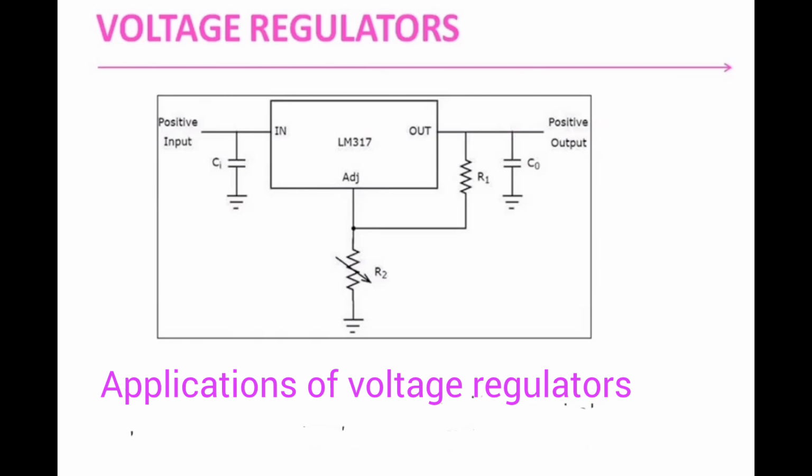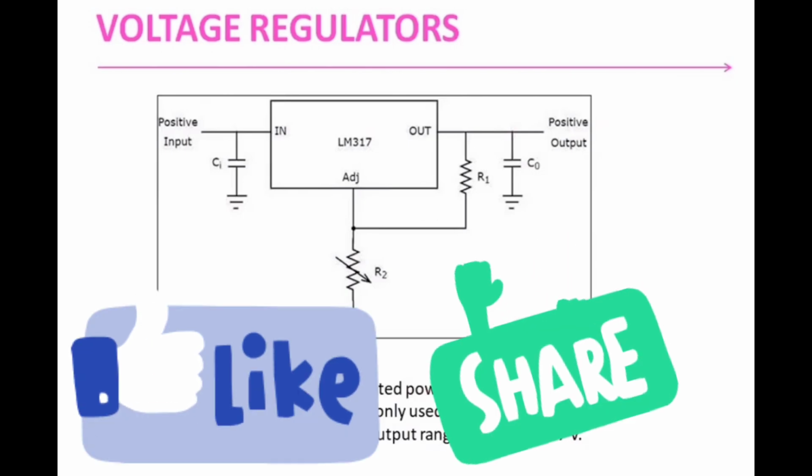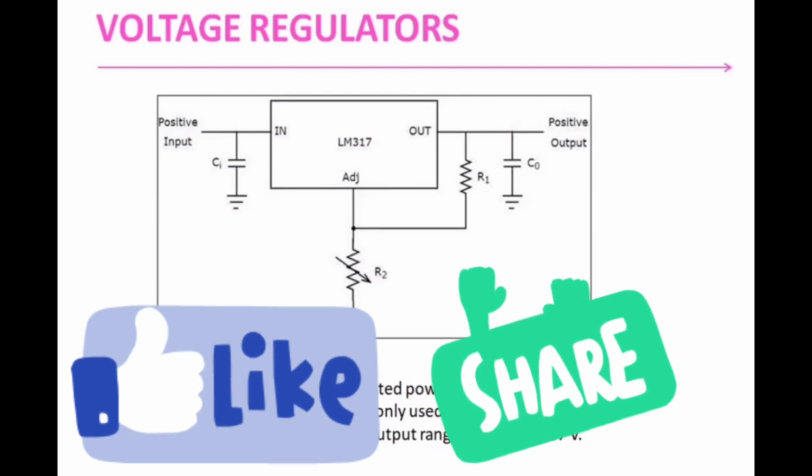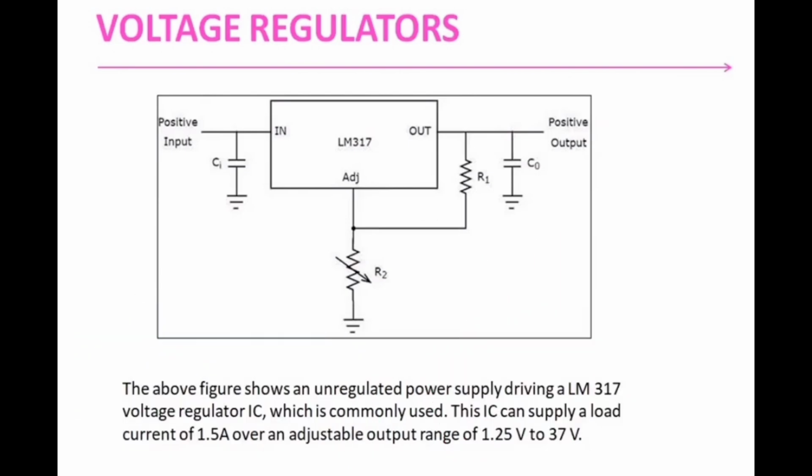And if you want to operate the operational amplifiers, you can see they require positive 12 volt and negative 12 volt. So I require IC 7812 and 7912 for the proper operation.